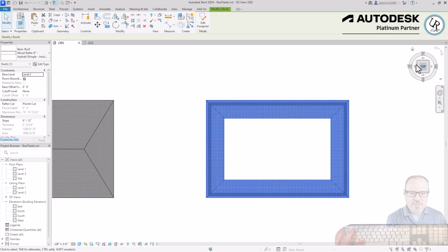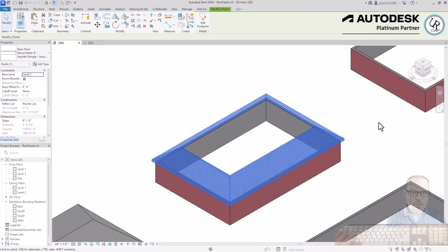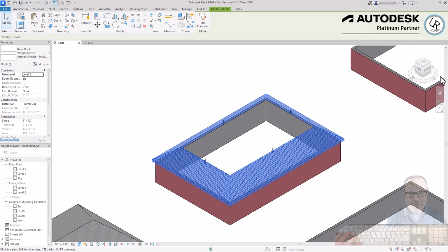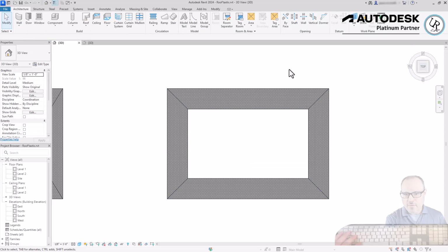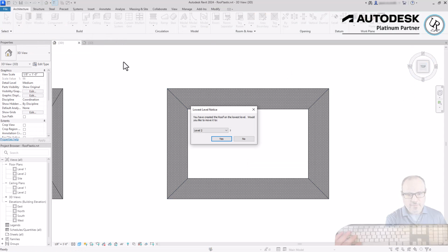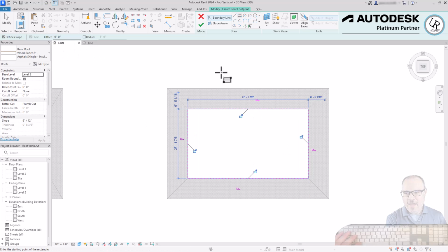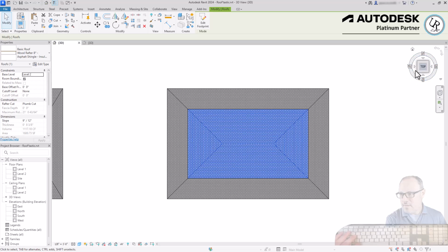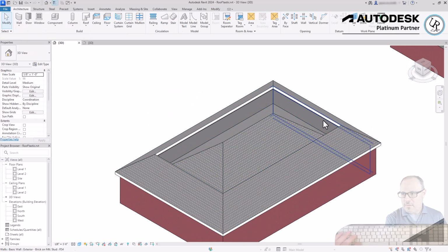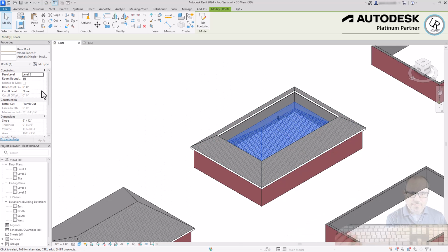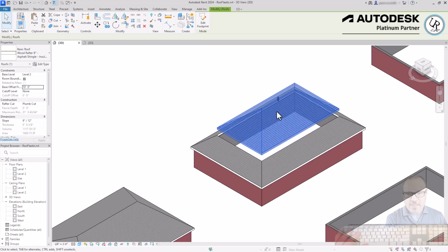So there should be a hole or opening within that roof design at the top. When I click on that and tilt up, the roof will actually show an opening or a hole in that space. And we'll add another roof location on top of that. But as you'll see, it's kind of difficult to set the height correctly. Choose roof again to level 2, roof pitch, within that same opening of the rectangle, and then click the green check mark to finish and tilt up. And as you can see, the roof inside of the other roof is actually lower than the one next to it. So we need to adjust that, and one way to do so is to change the base height so that it's actually above the roof so we can select it more easily. So I'm going to set that to 10 feet.